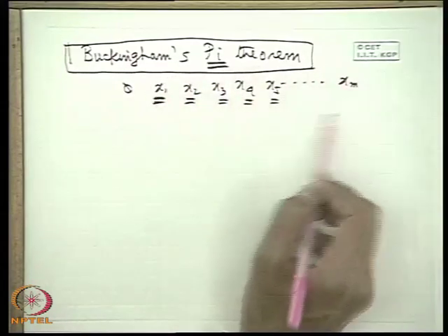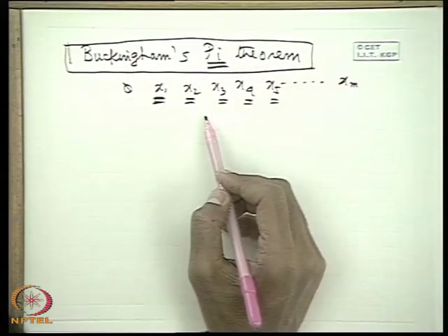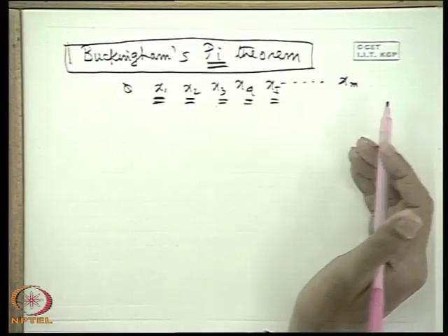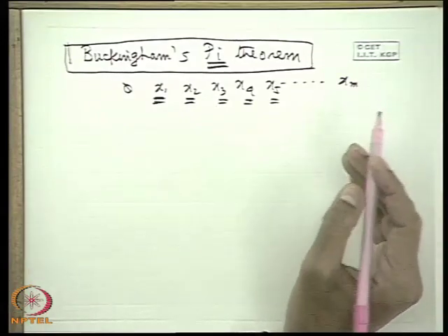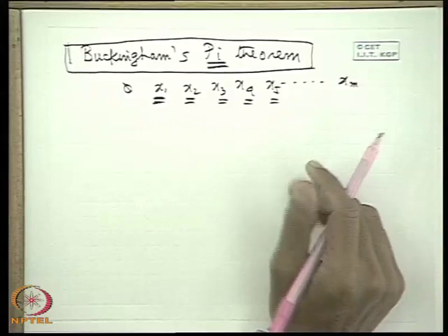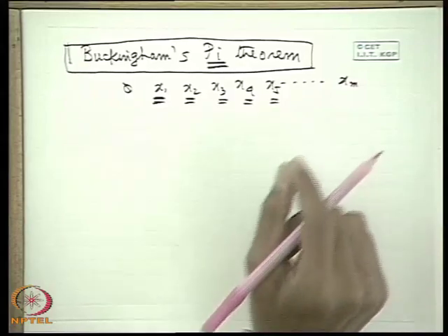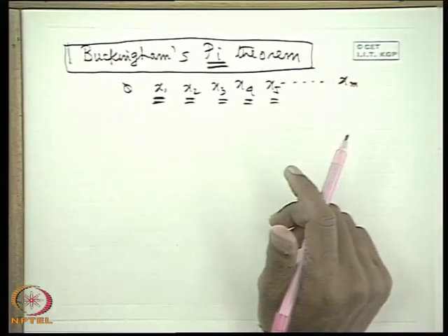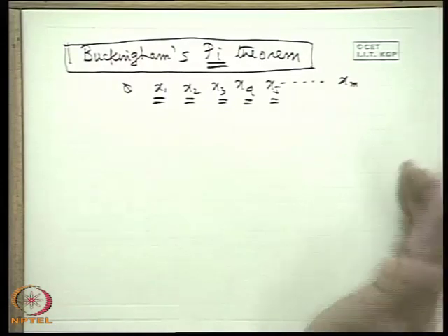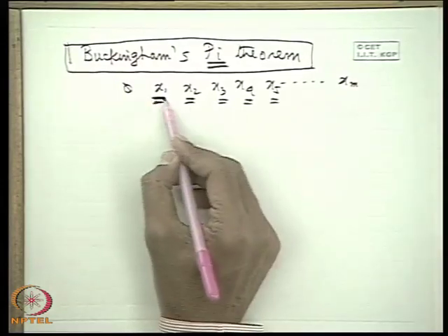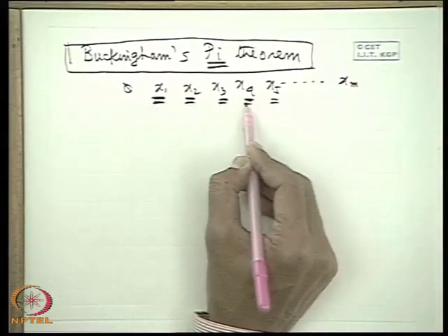If we fail to recognize, very important here, that surface tension is one of the dominant variables which plays the role in case of flow of a free jet or flow of a liquid of a very small diameter, in the order of 1 millimeter or less, that is our fault. So we will have to find out what are the physical variables that control the flow.